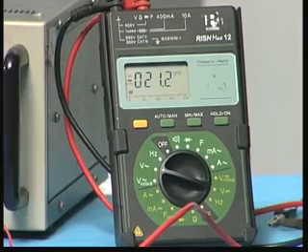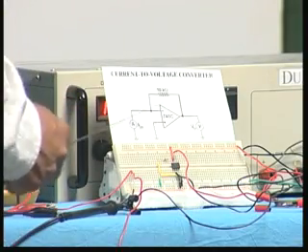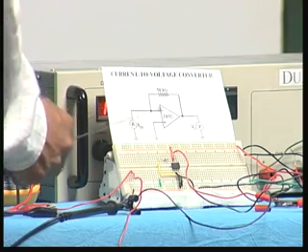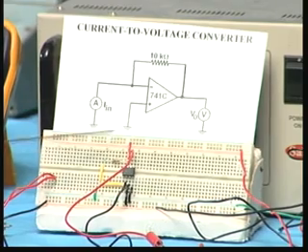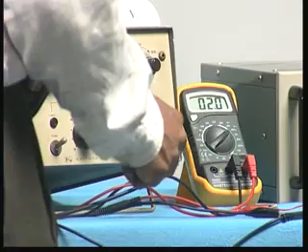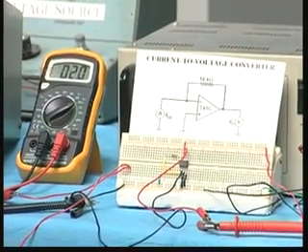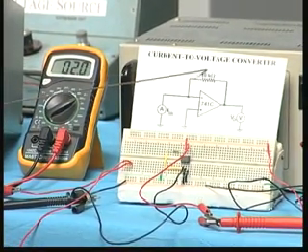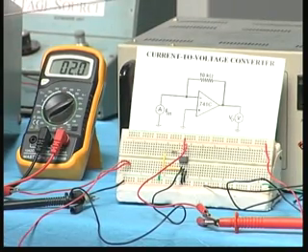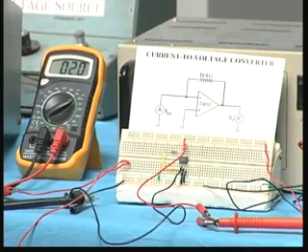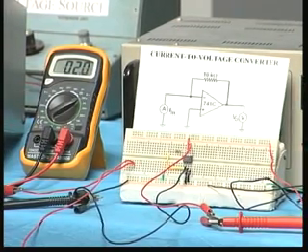So if I want to change the conversion factor, the conversion factor is basically the 10 kilo ohm, that is a transresistance amplifier. So if I change it to 100 kilo ohm here, immediately you will find the same current will be multiplied by 100k and you will get the corresponding output voltage here. So you can increase or decrease this resistance here and get a voltage proportionally at the output. Therefore, it is a very simple and useful circuit, especially when you have a number of different sensors.